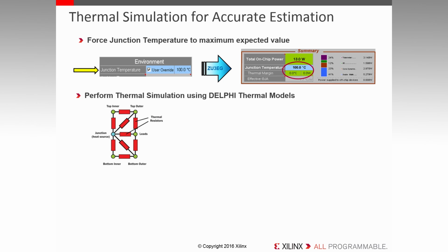A compact thermal model is a behavioral model that aims to accurately predict the temperature of the package only at a few critical points like junction, case, and leads. The Delphi compact model is typically the best representative model for packages and typically includes a representation of all the heat conduction paths. High predictive accuracy, portability, and computational efficiency make Delphi CTMs the most suitable for semiconductor manufacturers. That is what Xilinx intends to offer in support of package thermal analysis.